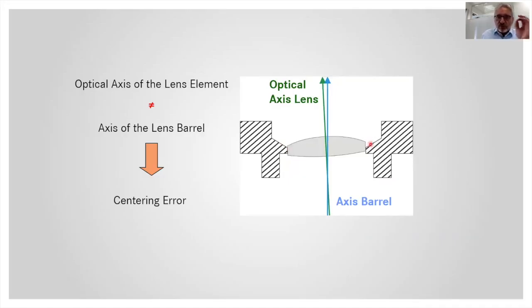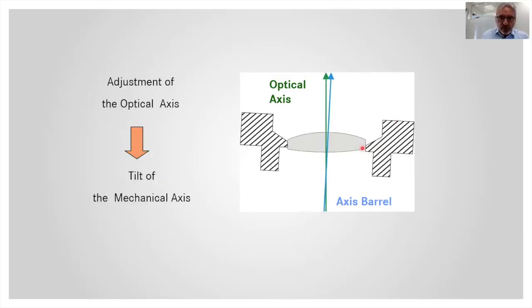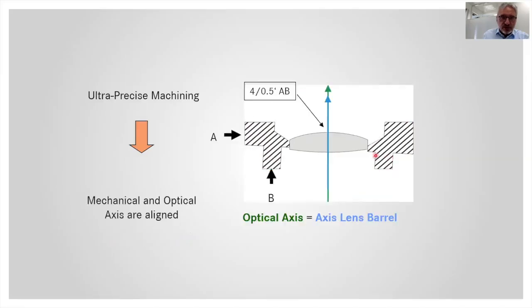To get best performance, we developed a lot to get higher precision. For example, we put the lens within the barrel, and then we machine this part afterwards. After assembly, we do a final machining or final adjustment of the mechanical parts. So we get highest performance and good tolerances for the lens element within the housing. And then we can align, yes.